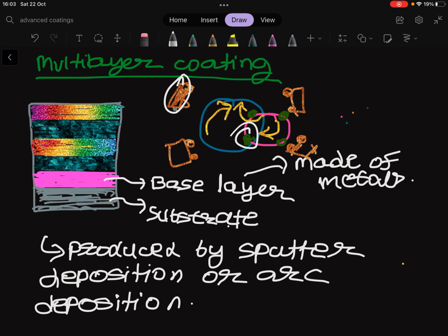The half circle on the rectangle is the path of the magnetic field lines, because as we said, we exploit magnetron sources. Then we have magnetic confinement. We produce a specific path on the surface of our target where electrons are confined, and in this region we have localized erosion. So this half circle represents firstly intense magnetic field, second electron confinement, third the localized erosion.